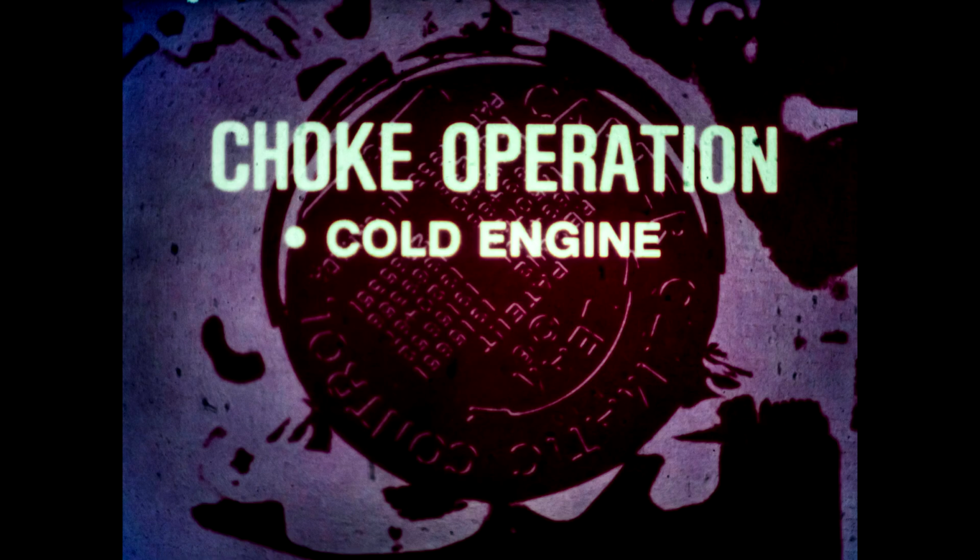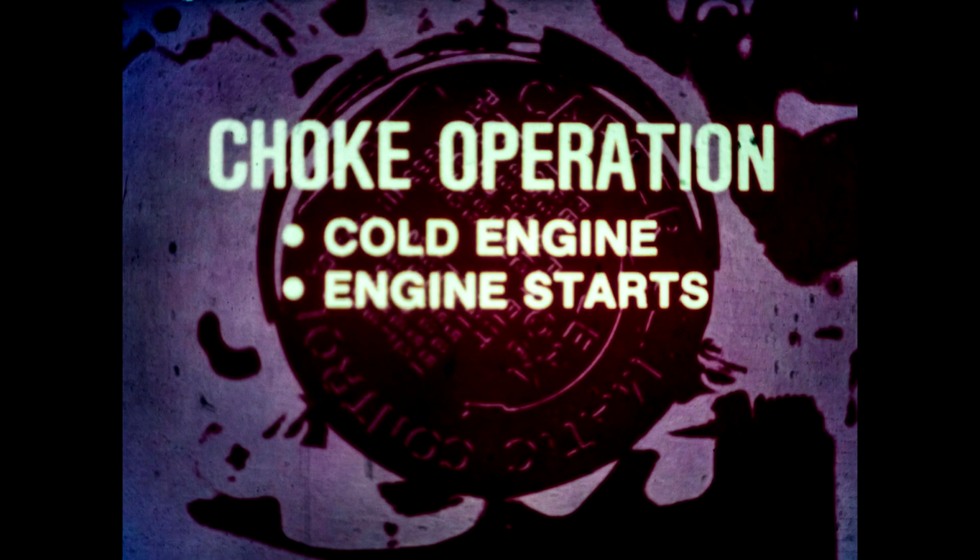Now for the choke circuit. There are different types of automatic chokes, but they all perform the same function. When the engine is cold, a tightly coiled temperature-sensitive bimetal spring closes the choke valve, which reduces airflow to the engine. When the engine is started, manifold vacuum opens the choke valve a predetermined amount.